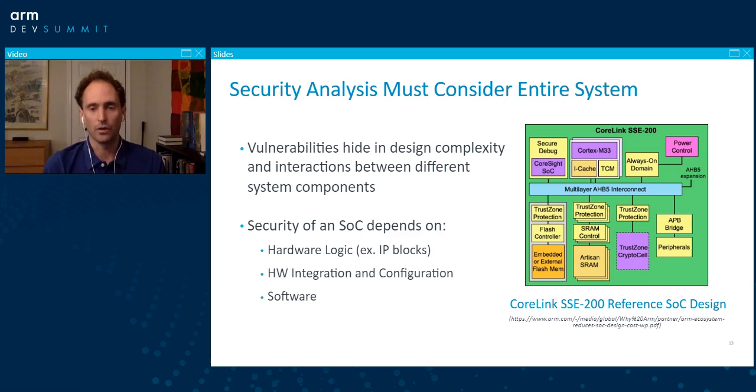As you know, a modern SoC has very complex hardware blocks. Within a respective IP core, there could be security concerns. As you stitch a lot of those IP cores together into a larger system, there are a lot of hardware misconfigurations that can go on. Things can get unconnected properly. We've seen customers incorrectly ground privilege bits and escalate privilege accidentally. And then there's obviously the whole system software configuration. As the system boots and gets configured, that also introduces a lot of potential problems. So it's really important to look holistically at the entire system.